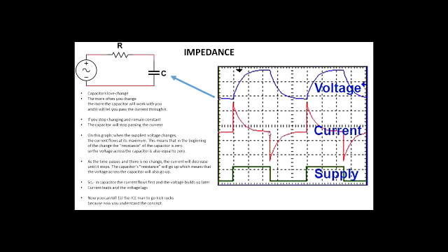Then we change the voltage again. Here's another change. So the current flows the opposite way at its maximum, and as the capacitor discharges, or basically goes to whatever the supplied voltage was, to that level, then the current stops flowing because it discharges. And it just repeats like that if you apply a signal like this, okay?